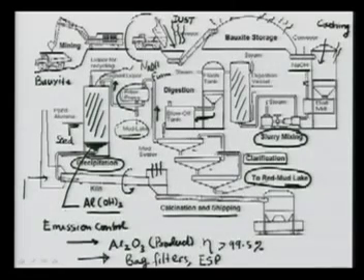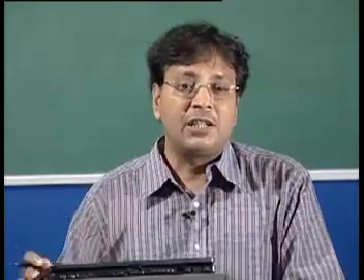in here. So whenever we were making the aluminum hydroxide here, the NaOH was recovered, and that recovered NaOH is recycled back to here, as you see. So this is, in brief, the aluminium, or rather alumina, production process. And so what we can quickly see are the sources of pollution. That's what is of interest to us.